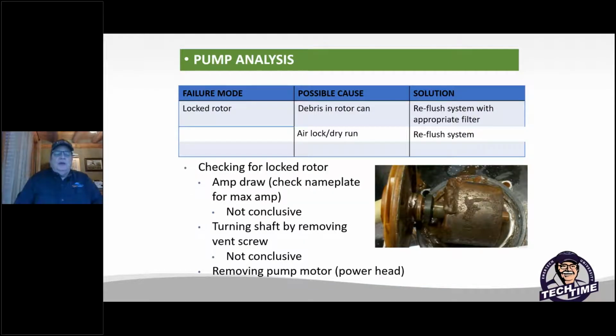You take a look at the sludge and garbage that's inside this pump and system. Kind of shows you the reasons why, the importance of adding a protective chemical in there. These create service calls, create service problems. If you plug up radiant floor manifolds, plug up fan coils, all this kind of stuff. So the importance of doing a protector is immensely, readily seen. So please think about that, keep track of it, do a good job.